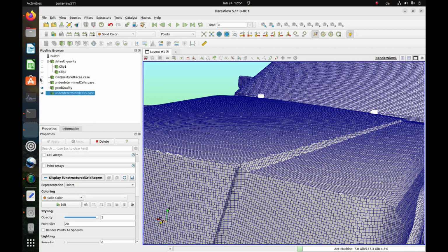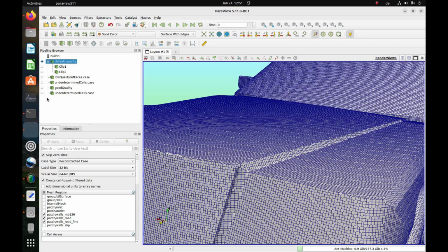Here, and let me show the default settings. So the previous one, it is not much difference what we can see, but let me run the last simulation in Snappy, where we can define our quality. And now I will try to create the mesh with best geometry reproduction.